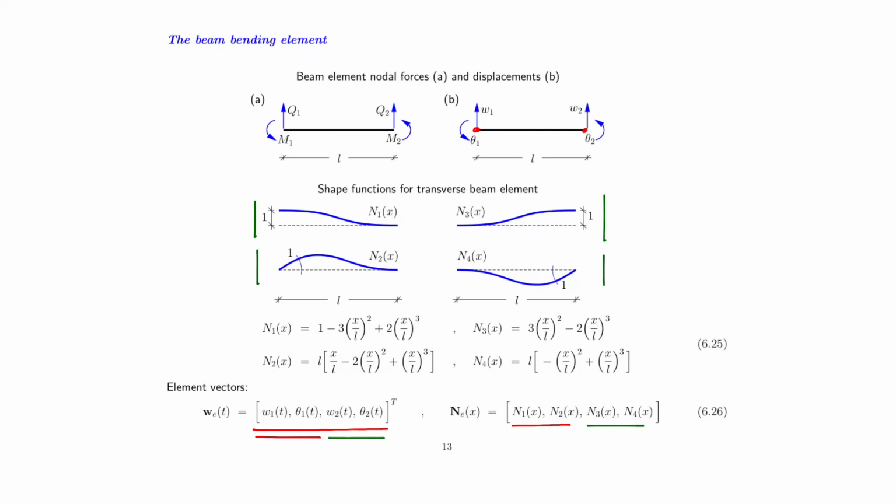Look up in any finite element handbook, structural mechanics book, whatever, you will find that cubic shape functions will be sufficient to interpolate a beam problem. And the reason for that is that the section force with the highest order of derivative will be equal to the shear force, and that we need to differentiate 3 times. Thereby, cubic shape functions will give us constant shear force along the element and a linear variation in the bending moment. And that is sufficient for our interpolation.